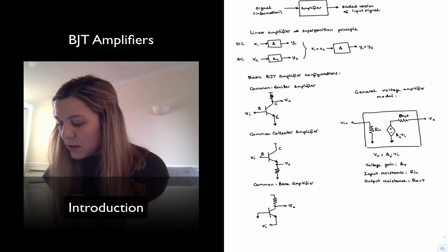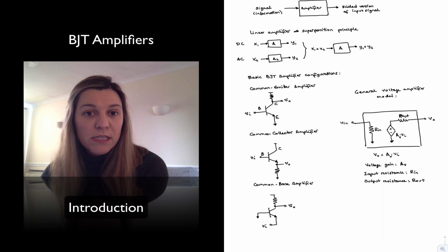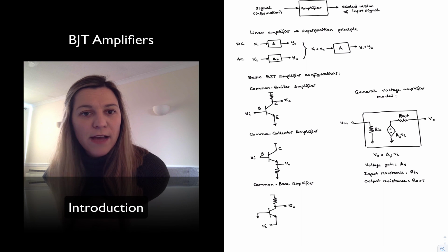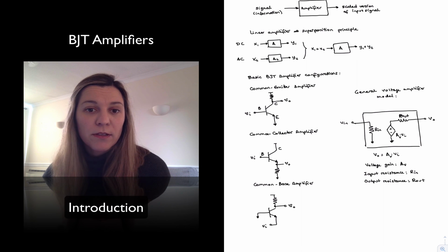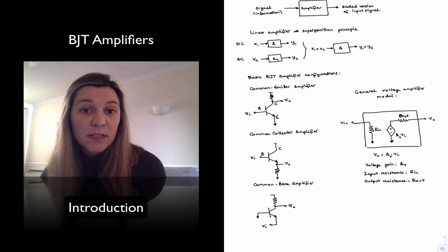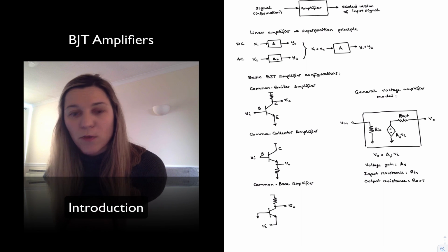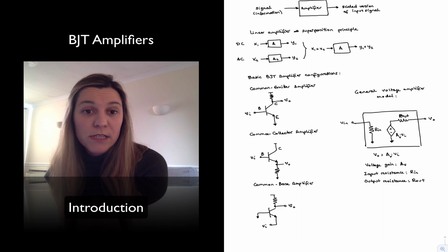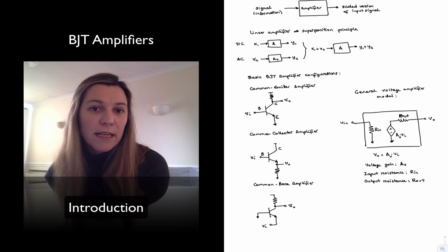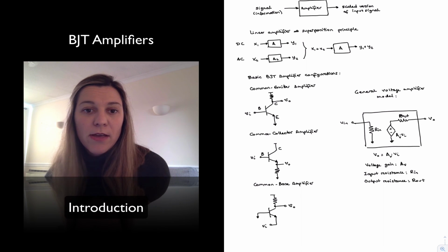So basically, the input resistance is modeling that if we connect an input voltage source, that source is going to have a series resistance, and how is that going to affect how much of the input signal gets transferred to my amplifier. And likewise at the output, I may want to connect a load resistor, or any type of load that I model as a load resistance, and the output resistance will tell me how much of a loading effect, or a decrease in my effective gain, I will get for different values of load resistance.